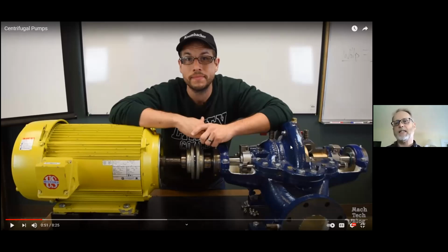This is the pump casing. The impeller is situated tightly inside. You can just see the wearing, which he's going to talk a little bit about and we'll cover off inside. And then again, the shaft moving through. So this is basically a split case centrifugal pump because it's split along the axis, which is parallel to the shaft.